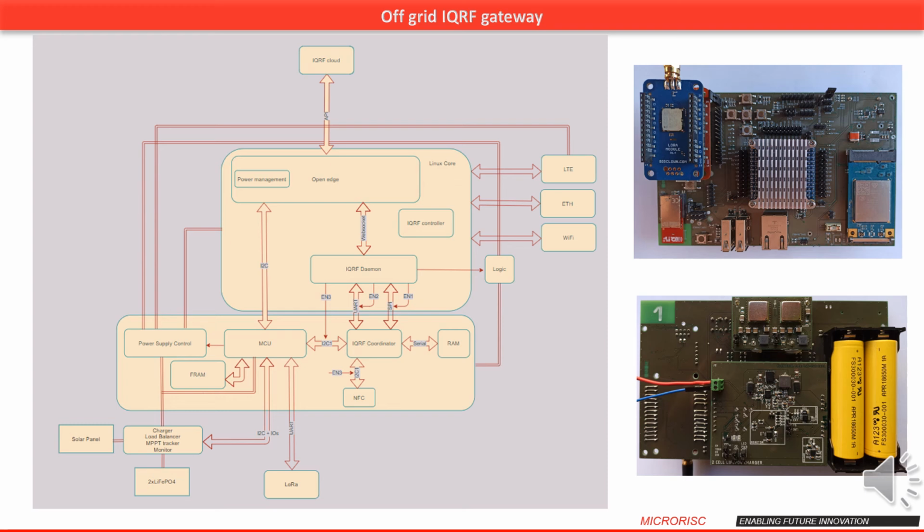Therefore, in this design, a great effort is put into the system to minimize power consumption. A strategy is chosen such that the gateway periodically switches between communication and sleep. In this way, the average power consumption can be reduced very effectively. It should also be said that while the gateway is sleeping, the Iqrf transceiver can be active and still receive and store data. The forwarding of the aggregated data will only occur when the rest of the hardware is activated.